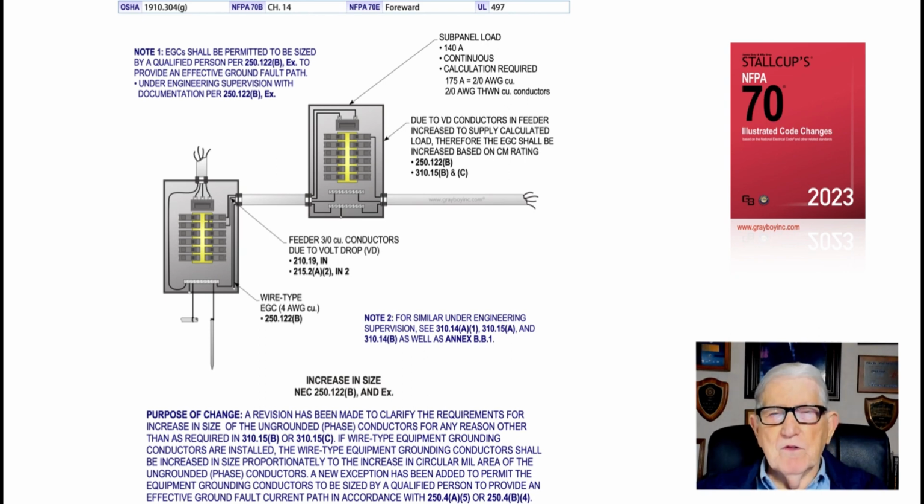Correction factors for too many current carrying conductors in a raceway, they would derate. And basically, what they wanted the folks to do... Now, you think about it. If I derated for correction factors, adjustment factors, and the 125% rule, I would have conductors that were sized, especially if I had a voltage drop problem, so large you couldn't even terminate them. And electricians would saw out strands of the conductors so they would fit under a lug, which was illegal, so it was just a problem.